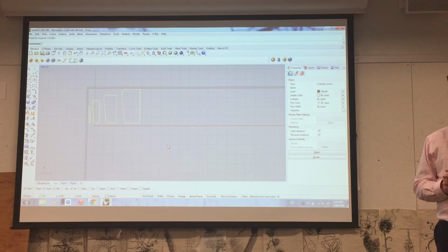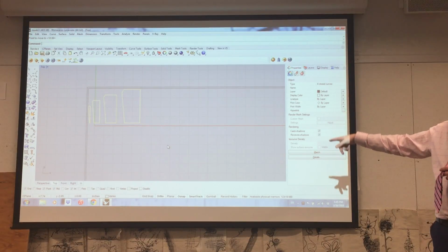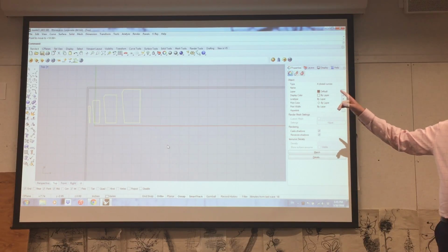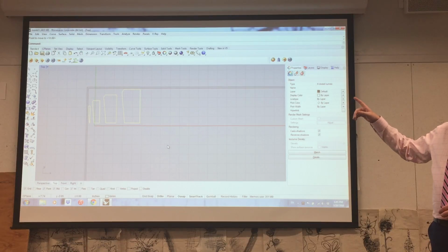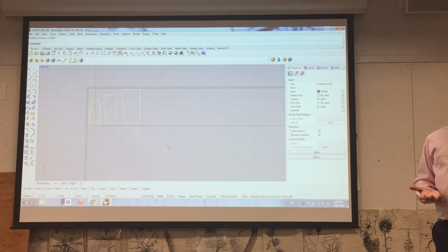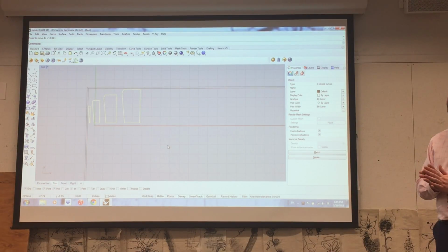What kind of file does it have to be? A DWG. So you'll save this and then just export it as a CAD file. And then depending on who does it, they'll tell you what else they want to do. Generally, every section should be on a layer that is a red color. Usually red indicates cut. But sometimes it's yellow, sometimes it's black. It depends on the fabricator. So you have to coordinate with whomever you choose.